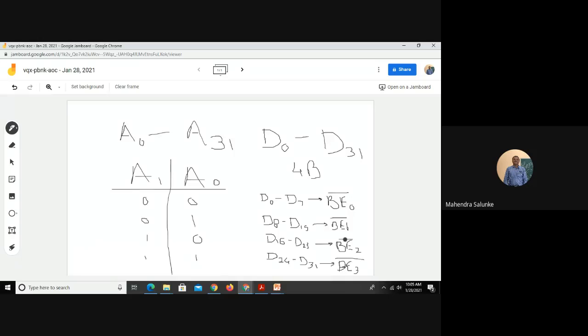All right. So this is the association of your byte enable signals and the respective data byte. Now, whenever it is expected to transfer a byte from given data lines, your processor is going to make the respective byte enable signal low, indicating that for the current data transfer, these data lines will be used.